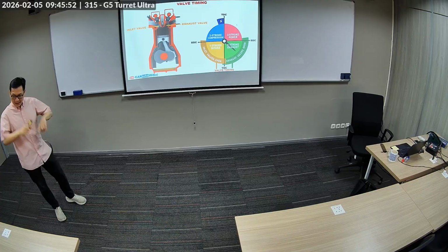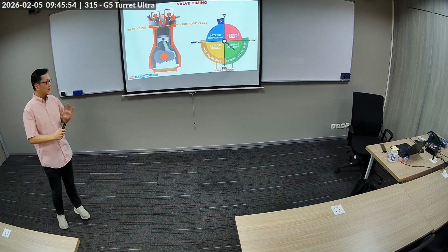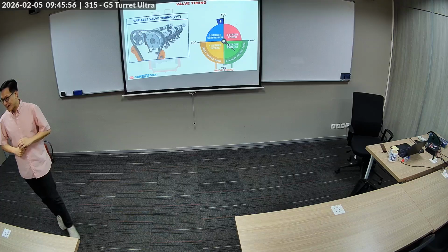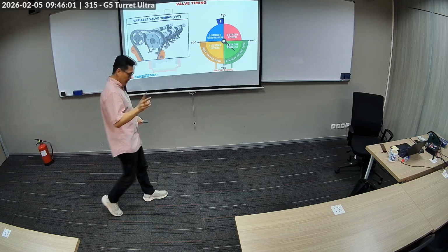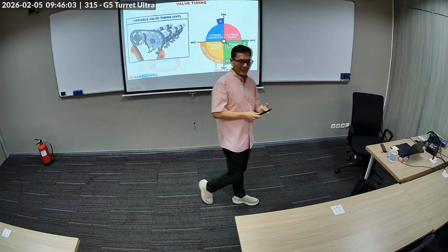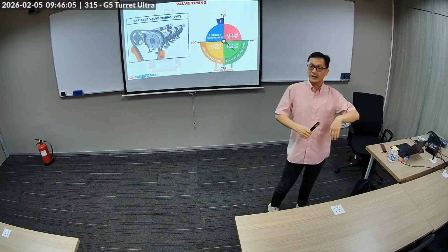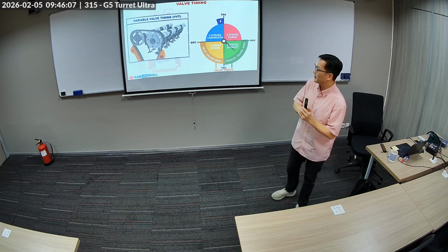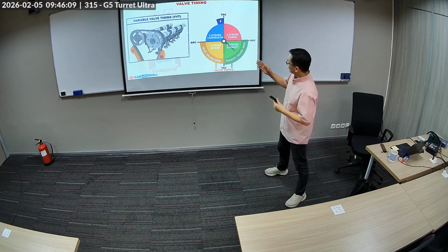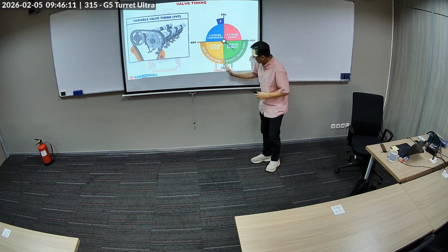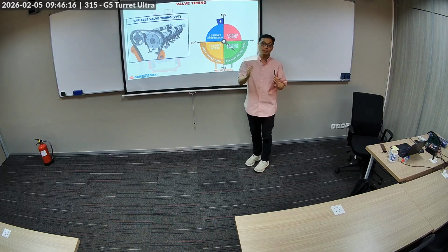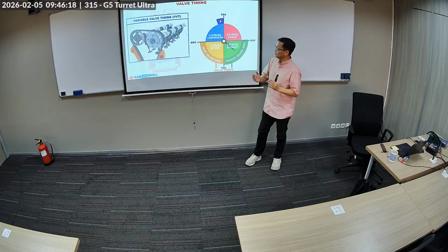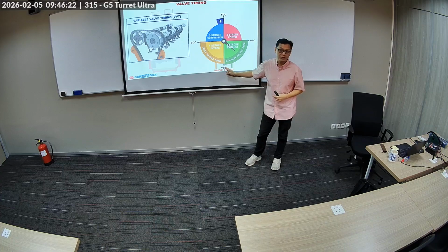Valve timing is controlled by the timing chain, but there is also variable valve timing, which is awesome. Two things that it controls. First, the valve opening, bigger opening for higher RPM, but also the timing. So the timing, how much overlap, is also optimized for the RPM range that you want. This also helps pollution, by the way.